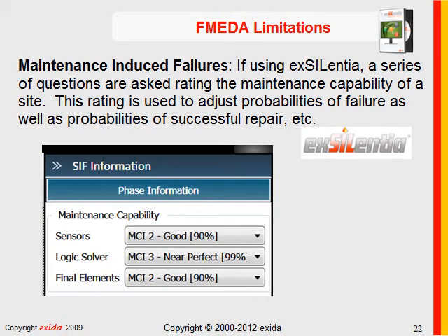One of the reasons for that is that the control room equipment often has better maintenance capability than field equipment. And it's not just the operating environment, it's that people do spend a lot more time paying attention to the controller, especially when its failure may take down an entire plant. I mean, the critical nature of the device dictates that it get high maintenance priority.